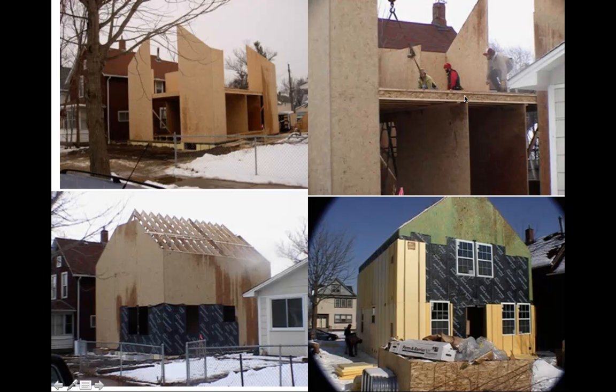So in a sense, this flooring system ends up serving two functions. In addition to supporting the load up above, it also is the buckling support for this, so that the height of this column is actually much less. Now, one wonders, okay, so why did we build a house like this, or why was this house built? One of the reasons is looking at a different type of basically weather protection and insulation system.